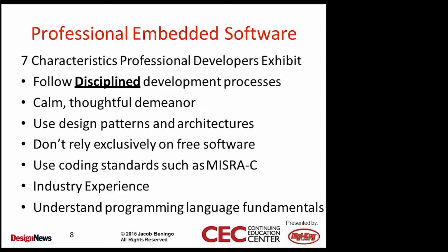Use design patterns and architecture. A lot of times what I find is that people who are maybe just entering the profession, coming right out of college, junior engineers, they're not really following design patterns. And these could be simple things like the way in which you set up a UART to bring data in: push the input character, use an interrupt to grab the character, put it in a buffer, and then set a flag somewhere to come back later and check to see if the buffer has been filled enough to decode a packet. Very simple design pattern, maybe even bootloader design patterns, things of that nature. There are these solutions already out there, and as professional developers, we try to leverage those as much as we can.